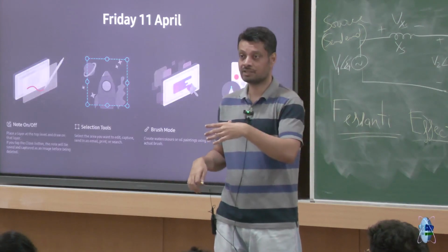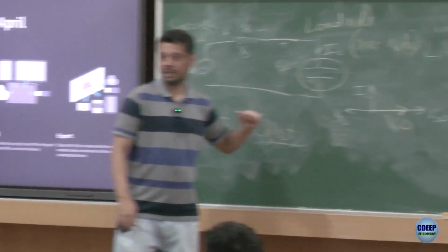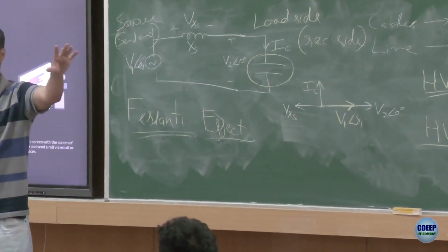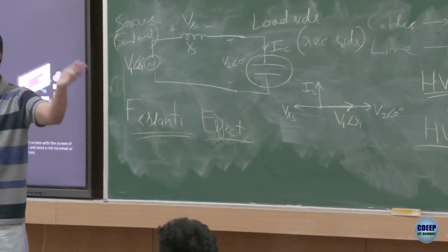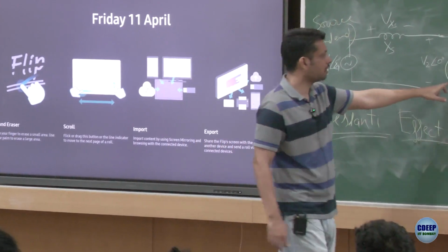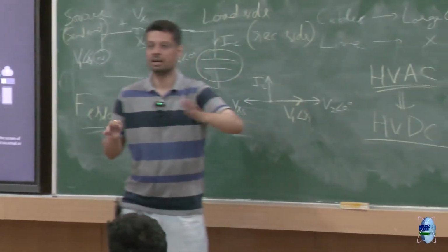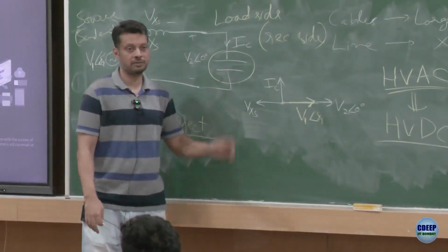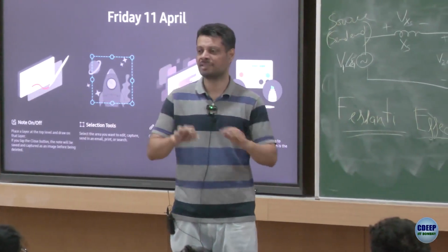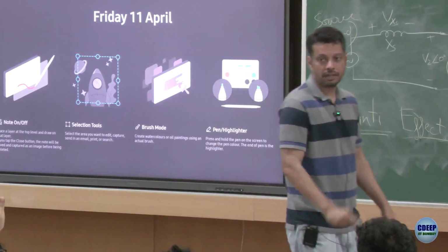Because you use cables to bring the power, you have the same problem. Therefore, there are people who talk about connecting the offshore farm using DC instead of AC. For the same reason, because cables you would not use for anything longer because of the excess loading of the capacitor. With the same principle, a lot of reasoning and thoughts can get connected. Last question for today.